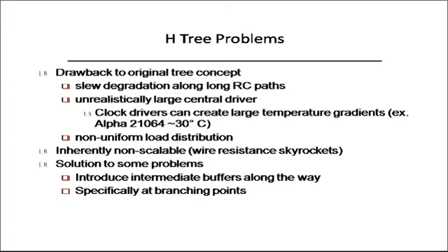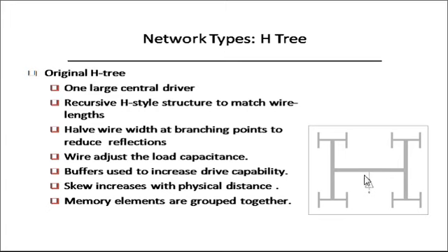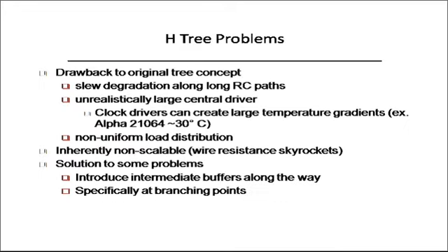Unrealistically large central driver. If you see the figure, you will come to know that you have to apply a very high capacity driver at the middle of the H. Hence, the large central driver is required, and there is non-uniform load distribution. Some flip-flops at the end may not turn on. What can you do for this?